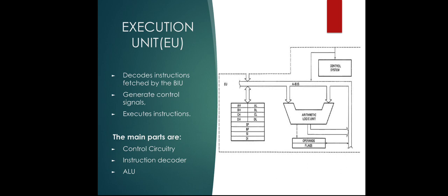Now let us look into the features of the execution unit. It contains a decoder. As I said earlier, from the instruction stream byte queue, bytes are taken one by one from the ISB queue and go into the decoder. The decoder is used to decode the hexadecimal opcode bytes into binary, and it is sent to the ALU. Finally, it gets executed.